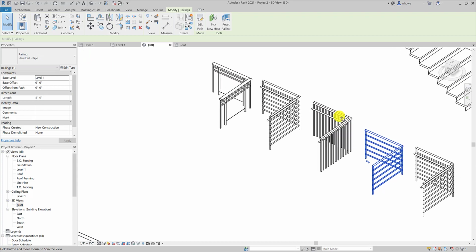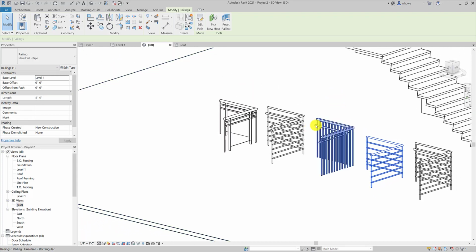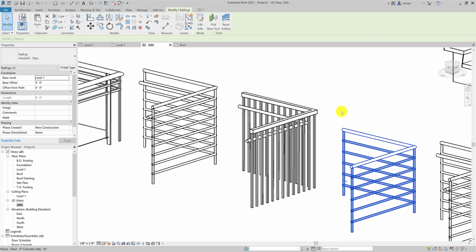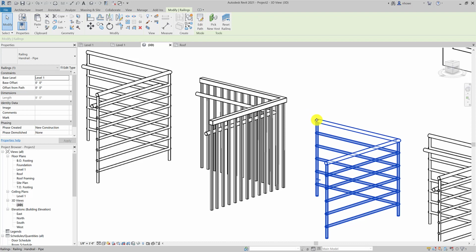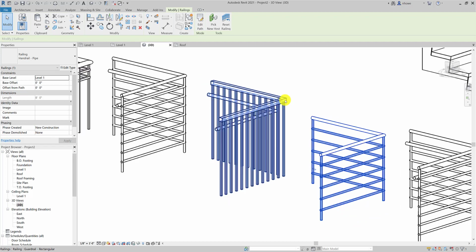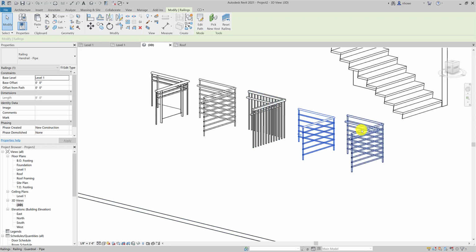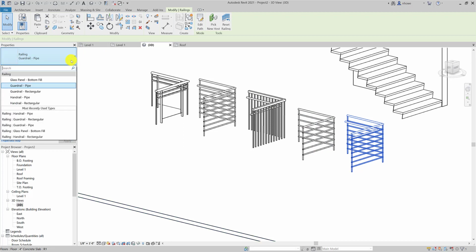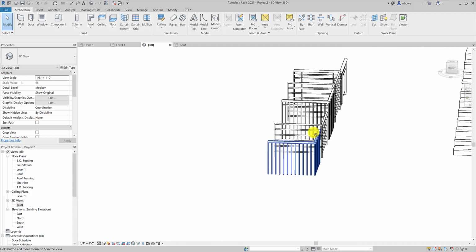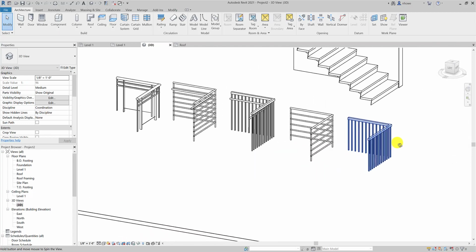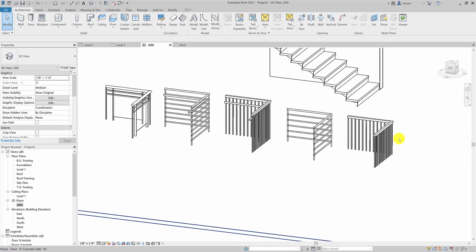Now you'll notice that once you get to the handrail, it's down here on these. This one apparently wasn't high enough in the air that you would need the guardrail. Again, that's a code thing. At a certain height you need to have another 6 inches, so this is probably at 36 inches and this is typically around 42. And then the last one is that. So each one of these might be a good way to start out depending on what you're trying to do.